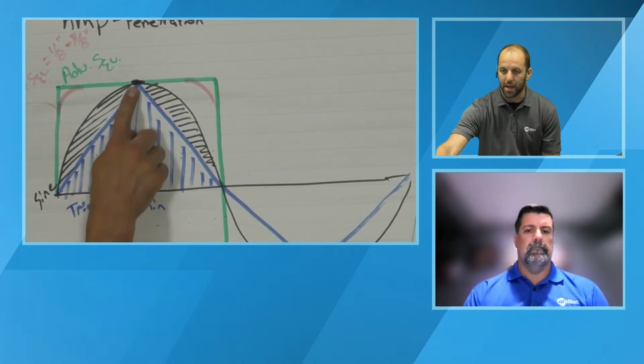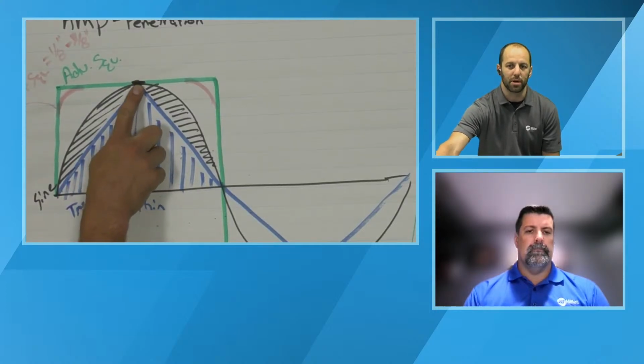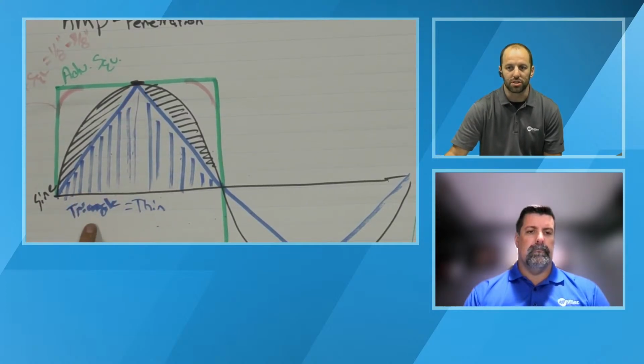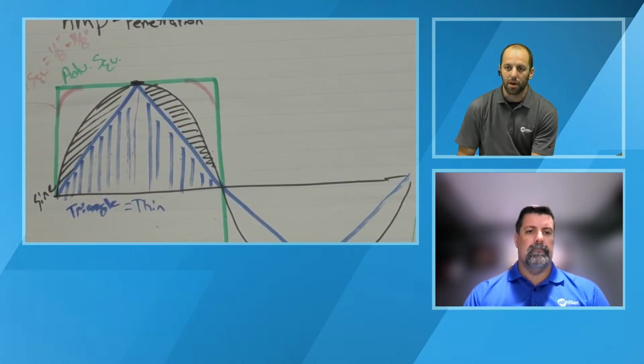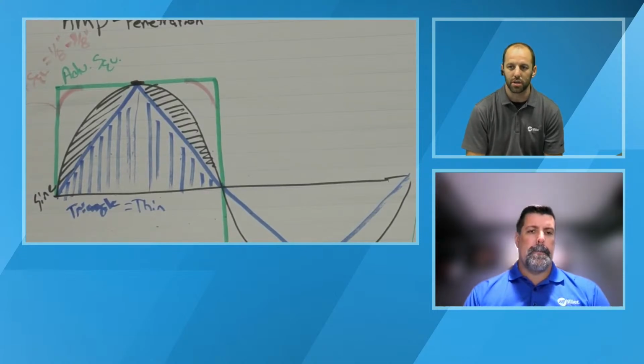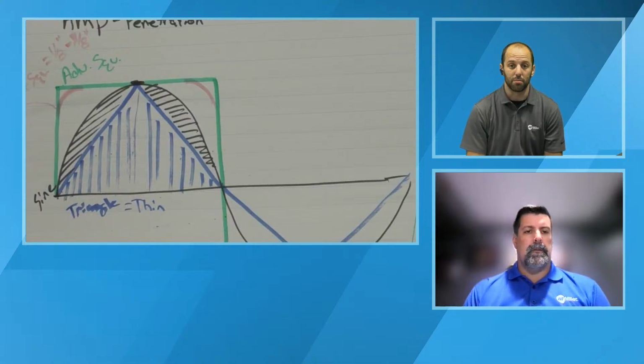In a triangular waveform, or this blue area here, you're still getting the peak to drive penetration, typically used on thin materials. As compared to one of the green boxes here, it's about half of the area, so about half of the heat being generated in the circuit. We're taking a majority of the heat out while still getting the penetration that we need on thin materials.